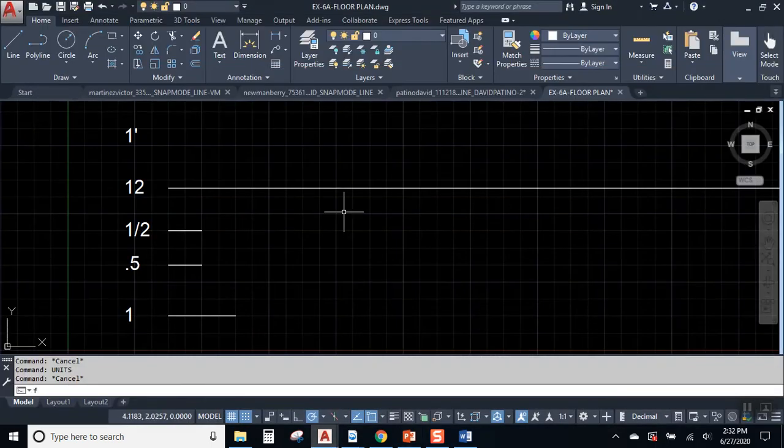Let's go make a fillet. I start the fillet command, and look what it says down here for the radius. It says the radius is 0.0000. If I say, hey, give me a 0.5 radius, 0.5. Now the new setting is set to 0.5. You see over here how we had 0.0000. So AutoCAD was talking to you to tell you that this is the setting that you currently have, and it was going to that 4th level of precision.